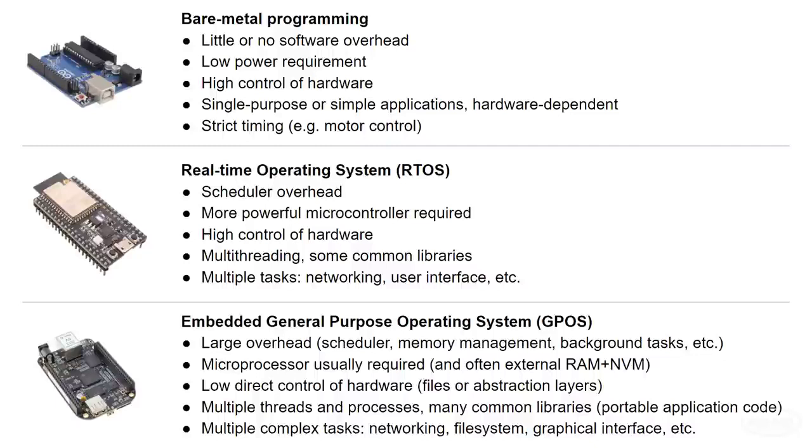Note that real-time operating systems do exist for microprocessor boards like this to give you better control over the timing of tasks, but you still don't have the same level of precise hardware control a microcontroller would give you. As a result, many chip manufacturers include a microcontroller in the same die as their embedded microprocessor. That gives you the best of both worlds. You can run advanced features like networking and complex algorithms on the microprocessor and low-level hardware control and timing on the microcontroller.